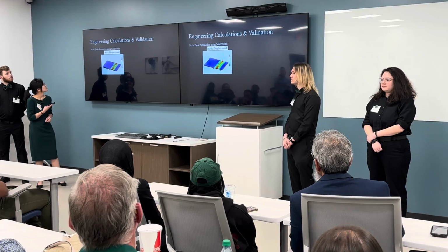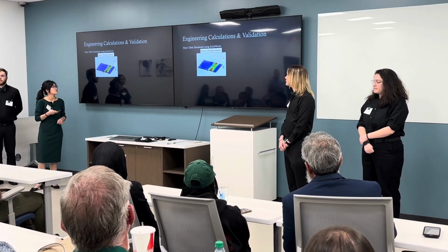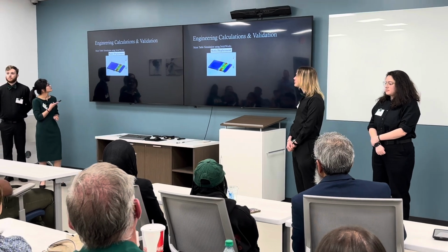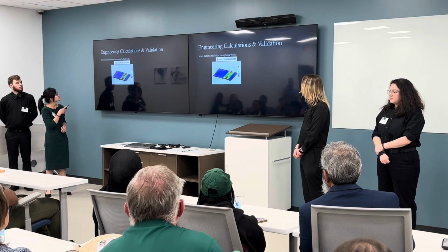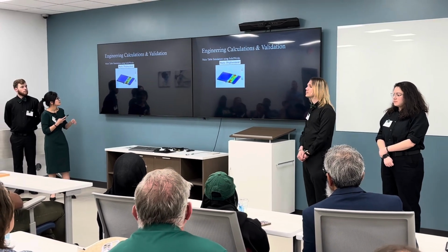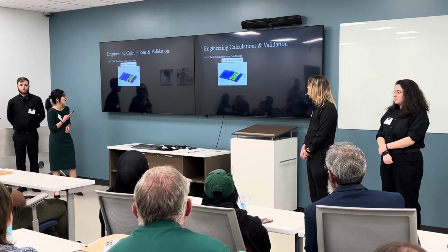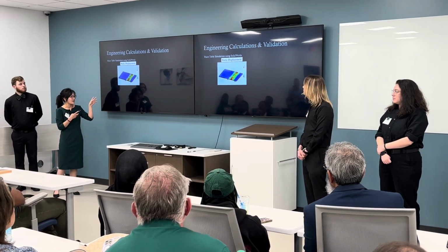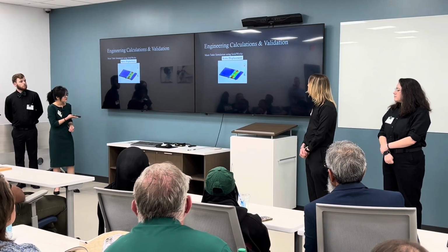And here's the main table simulation that we did using SolidWorks. The first picture is the displacement. You can see there is the red spot. That is the weak part, so we have two bars under the main table to support it.